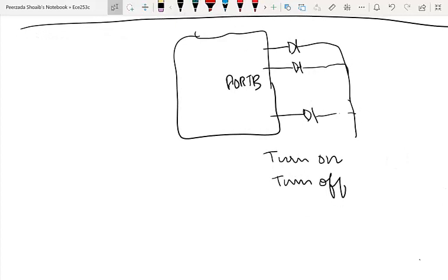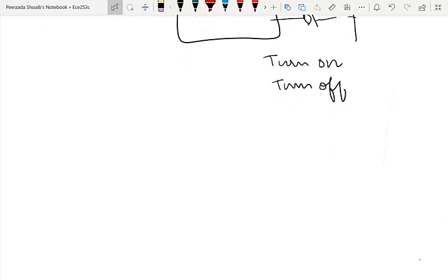Okay, so we have done this program in assembly language. What we did, first of all, we configured the port as an output port using the DDRB register, because we are dealing with port B. And then we write a number on these ports that turns the LEDs on. That number is 1111 1111, and then we give a brief delay, and after the delay we turn the LEDs off by sending 0 volts to all these pins. That's by writing the number 00000000. Then again some delay, then repeating the cycle. Simple. So let's try to write this code from assembly language in C.